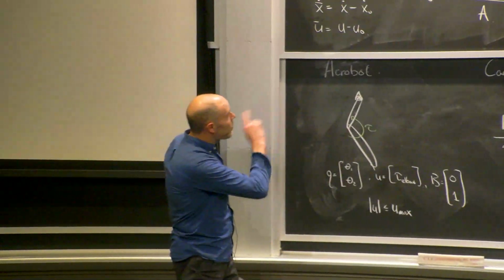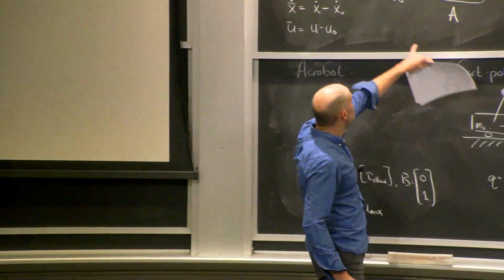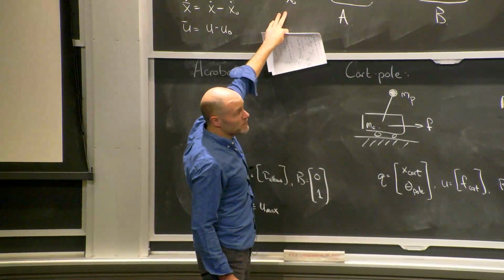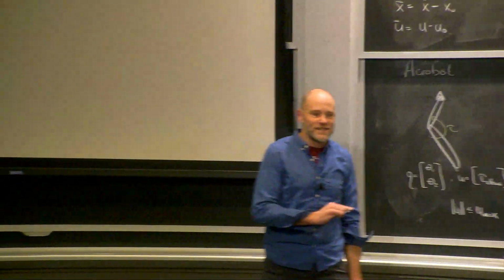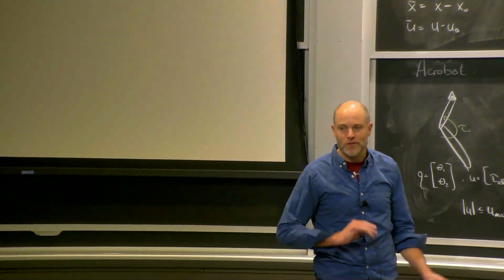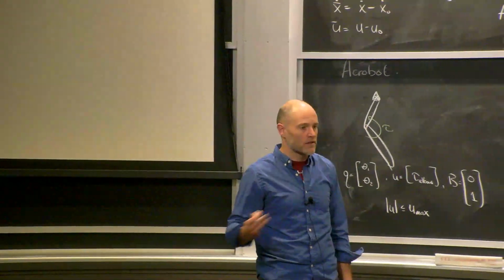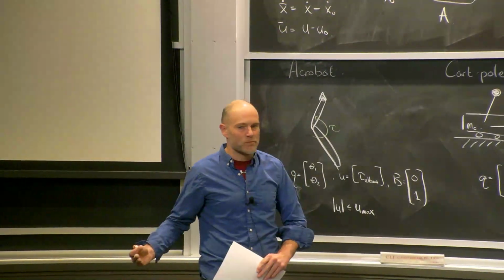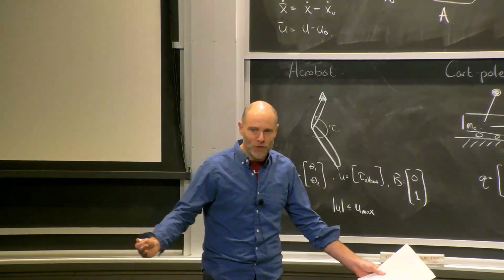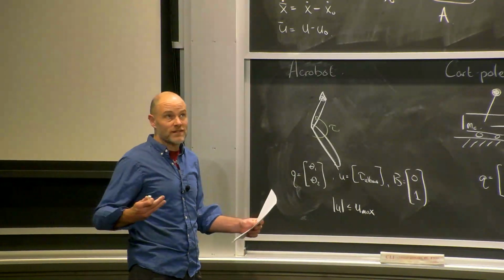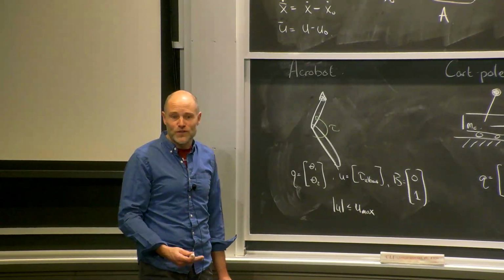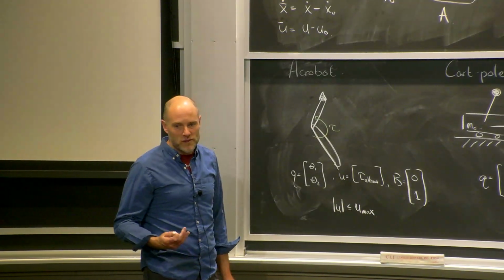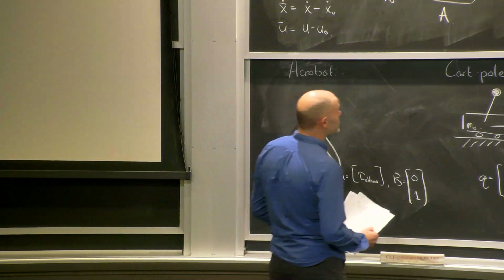All right, so yes, it's almost just a vanilla Taylor approximation, but we have to subtract out the error coordinates. The question is, how good is that Taylor approximation? For interesting nonlinear systems, the sines and cosines are the things that break our linearization. Like, how bad are sines and cosines, right? Basically, in all the rigid body systems, the nonlinearity enters through sines and cosines. That's the natural operator.